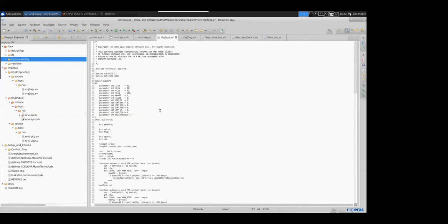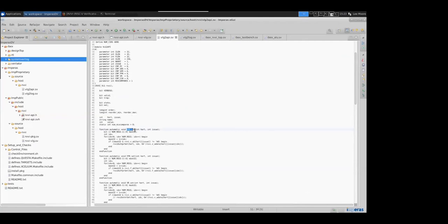So just to pull out a few simple ones, whenever we see a GPR value being set, then we have a function inside of this client which calls the RVVI DUT GPR set with the corresponding information for the given hart, the given register index and the register value. So that passes it automatically across for evaluation later when we tell the reference within the Imperas DV environment to say, okay, we've just executed an instruction or a sequence of instructions here. Please do the same on your side and tell us whether or not we have a difference in terms of the computation and the internal state at the end of the retirement.